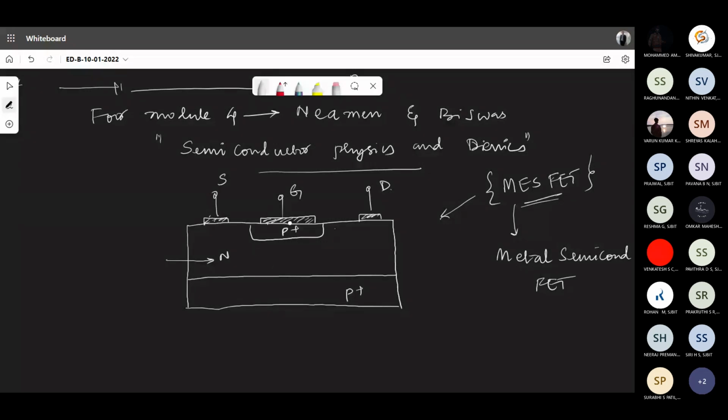And you can see the gate here and the substrate are made up of the same type, P plus and P plus. So now I can think of indicating the resistance between the source as well as the gate here. And remember, it is only up till this point. The resistance offered here is RS. Remember, it's a very small value because the actual current flow will happen only within this channel. So this is what we call the active channel region.